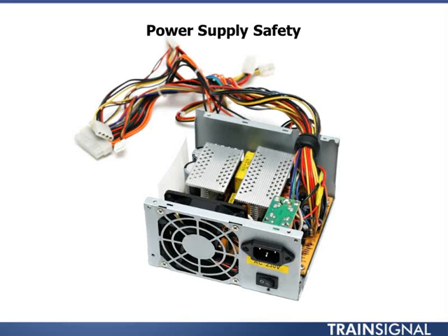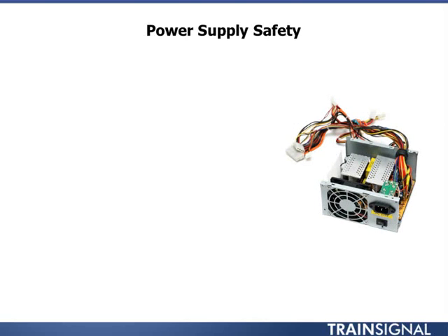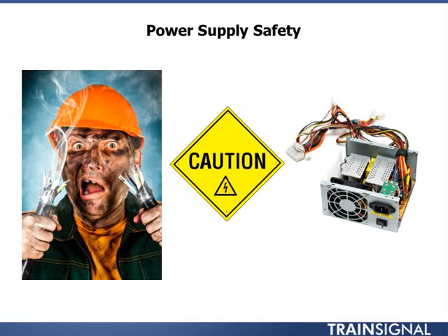Also, if you'll notice, this particular power supply is open. That's a bad idea. There are no user serviceable parts within the power supply. Many years ago, there used to be a fuse that you could replace, but honestly, it's going to be a lot easier just to replace the power supply than to try to open it and get involved with these different components that can actually shock you. In fact, power supply components are not FRU, which stands for Field Replaceable Units. And the bottom line is, don't try to repair a defective power supply. Because it's an electrical device, you have to use great caution, or you could end up like this fellow, with a nasty shock and potentially an injury. So always be very careful with power supplies.